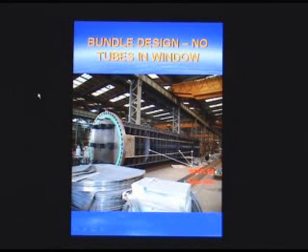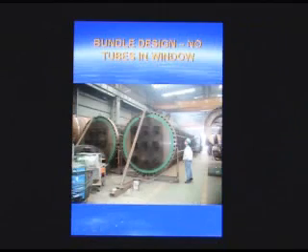So the same thing can happen within a shell and tube exchanger, and what will happen there is that the tubes will actually vibrate to the point where they can collide with one another. That will cause erosion points where the tubes are colliding, and that will lead to tube failure. So to give you an idea of how big that unit was, this was fabricated in Korea for an upgrade of the North Slope low temperature separation plant.